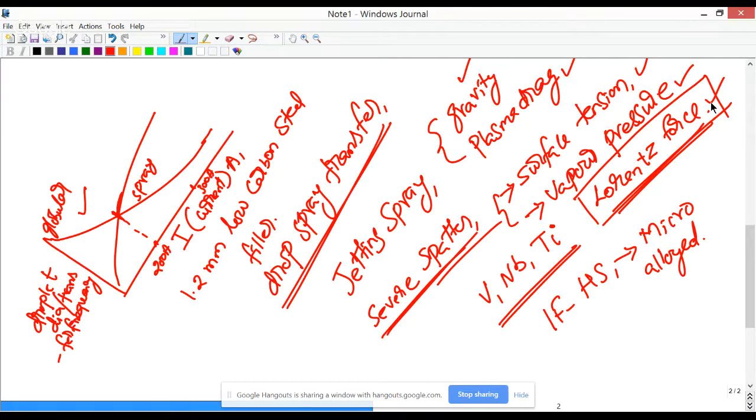And question number 5, boron increases the hardenability of steel because the answer is it suppresses ferrite nucleation. How does it suppress ferrite nucleation? Because the solubility of boron in ferrite is also very low. Same as how silicon and aluminum suppress cementite formation. So question number 6 in assignment 1.